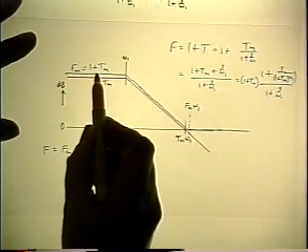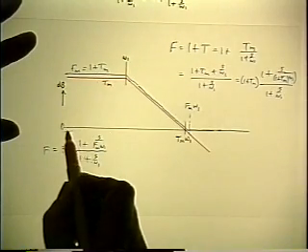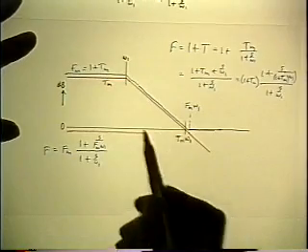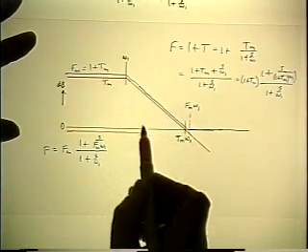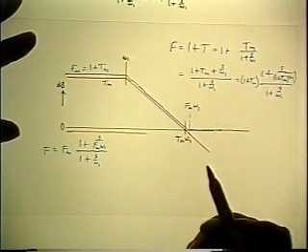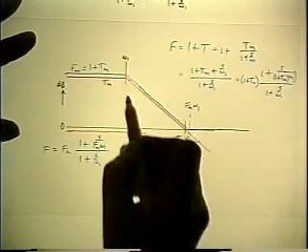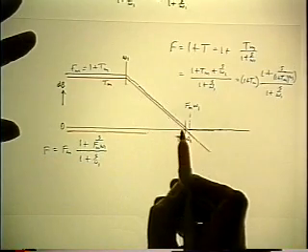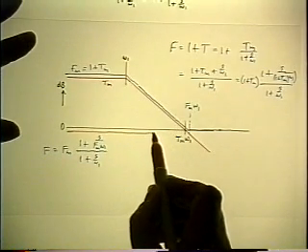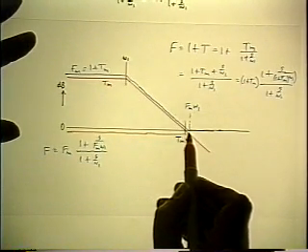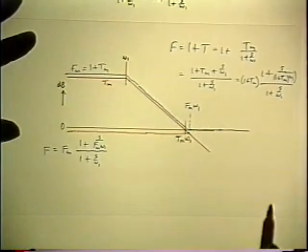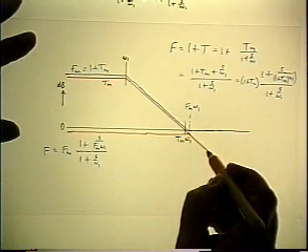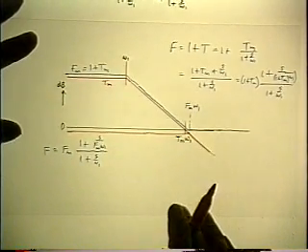So if I subtract the blue line from the red line, then I get a small negative number of dB. And since the blue and the red line have the same pole at omega 1, the orange line doesn't even show it. When I subtract one from the other, the difference is the same. And the difference remains constant until you get to this frequency where the blue line levels off and the red line keeps on going. And so now the orange line simply follows the T because the blue line is at 0.